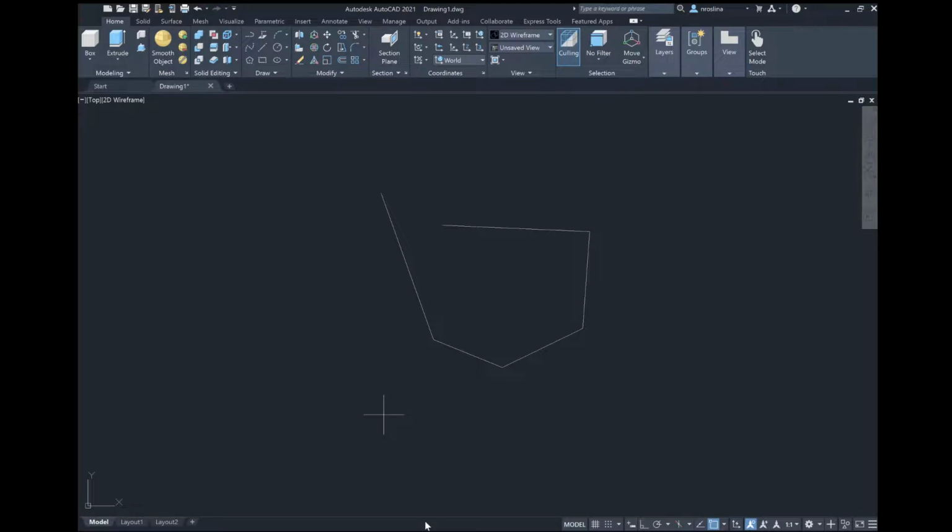And then it will ask me to enter the first distance or join type. I just press 0. Just accept it as 0. And then I'm done. I can just escape from the command. And if I click on it, you will see that it is now a polyline.